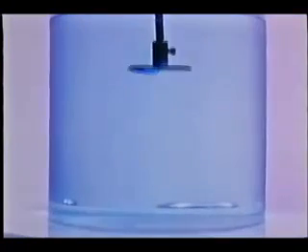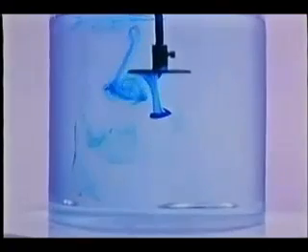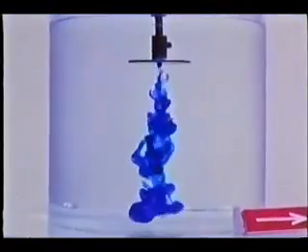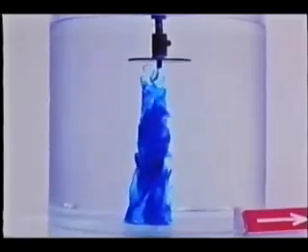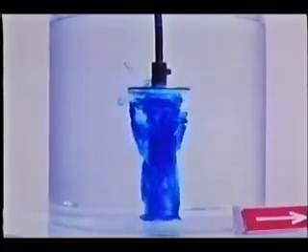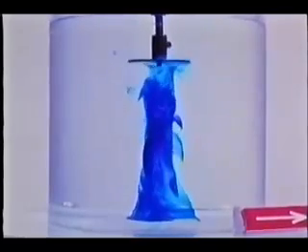First, when the fluid is not rotating, oscillation of the plunger produces a disorganized flow of vortex rings shed from one side of the disk to the other. But with rotation and excitation at the proper resonant frequency ratio of 1 1/4, we produce an internal inertia wave mode with a nodal plane at mid-depth. Such oscillations with frequencies near the so-called inertia frequency 2 omega are common in the oceans and large lakes.